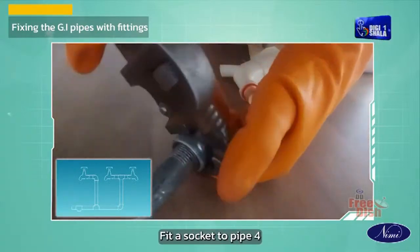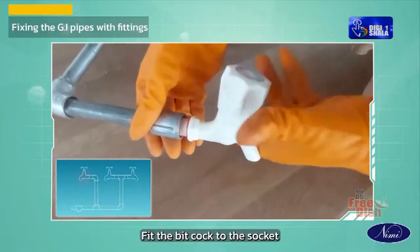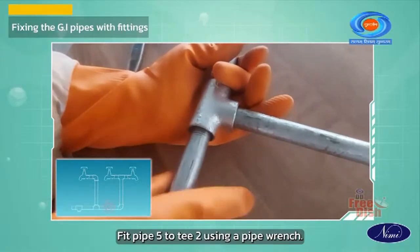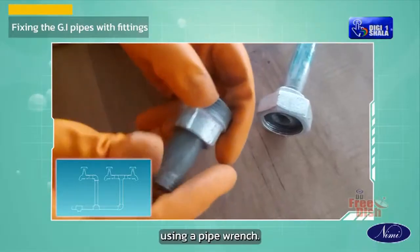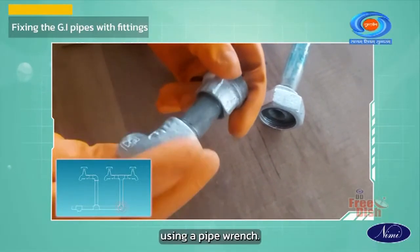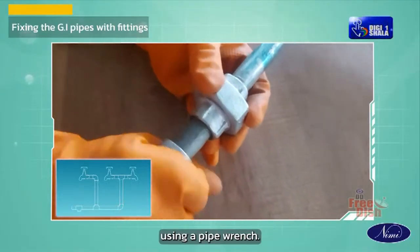Fit a socket to pipe 4 using the pipe wrench. Fit the bibcock to the socket using a pipe wrench. Fit pipe 5 to T2 using a pipe wrench. Fit the socket to pipe 5 using a pipe wrench. Fit the bend to the socket using a pipe wrench. Fit the socket to the bend using a pipe wrench.